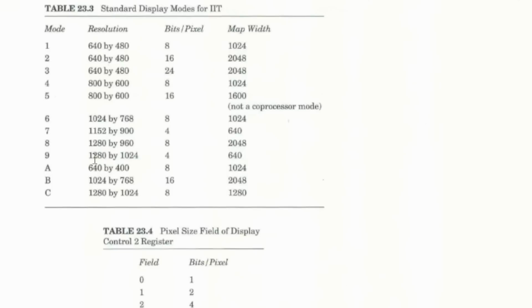And the most interesting thing actually is this chart of video modes. You can see there's some 800x600 modes which are not XGA standard. And there's also this 24-bit per pixel mode, so-called true color, which XGA didn't have. They did add that in XGA too, but I don't know whether it was supported by the coprocessor or not. Even the 16-bit modes were not supported by the coprocessor on XGA. But here you can see the only mode that's not a coprocessor mode on this chip is this one here. So it does look like there's some differences with XGA.